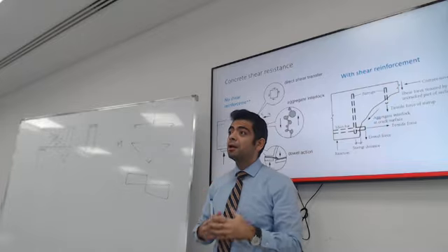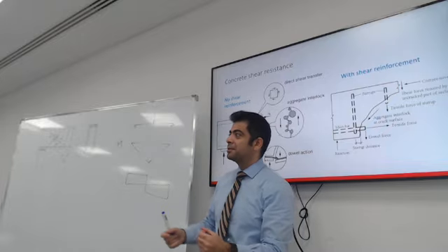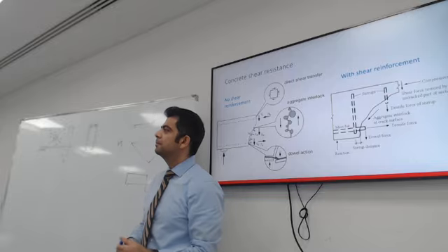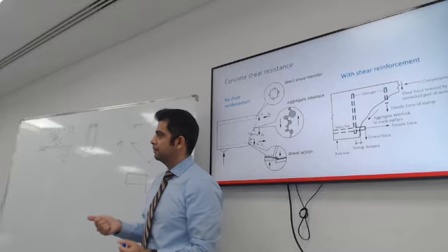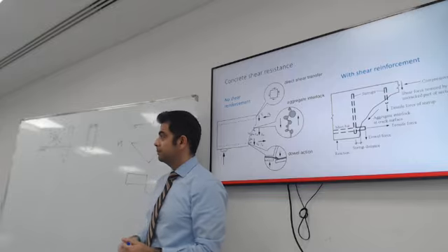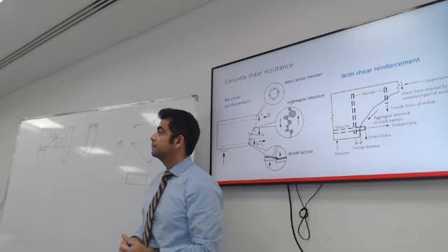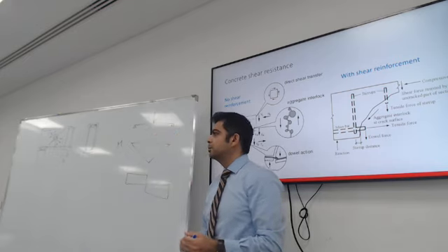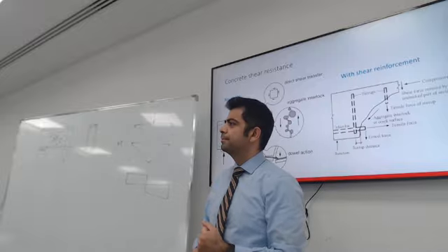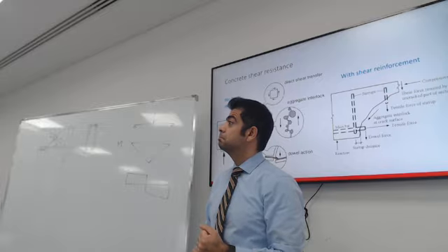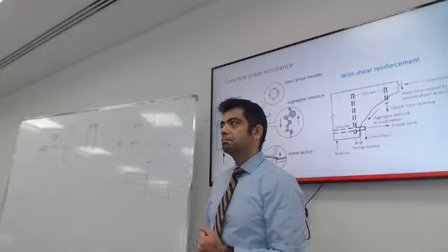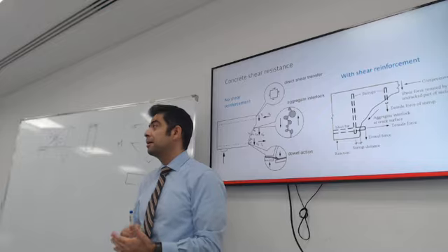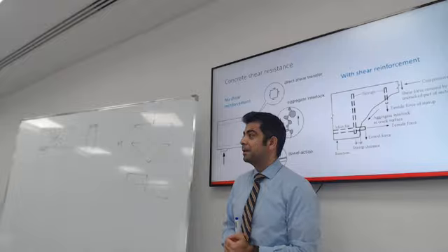What if I need more steel in the stirrup? We can either increase the diameter of the stirrup, thus increasing the area, or we can increase the way the stirrup loops. The way it loops, what do you mean? For example, if it's only around that, can't we interlock it in the middle? These are very good thoughts. Yes. Any other thoughts? Or increase the number of stirrups, like decrease the spacing.